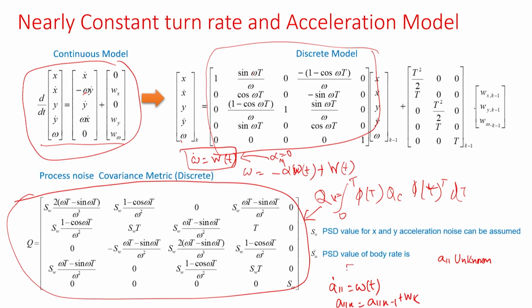It is your call, and it has nothing to do with your estimation accuracy. So, whenever something is unknown, you have to model it using a stochastic Wiener process or a first-order Markov process. Second order you can also do, but your state becomes unnecessarily complicated. So, this is one very important thing.